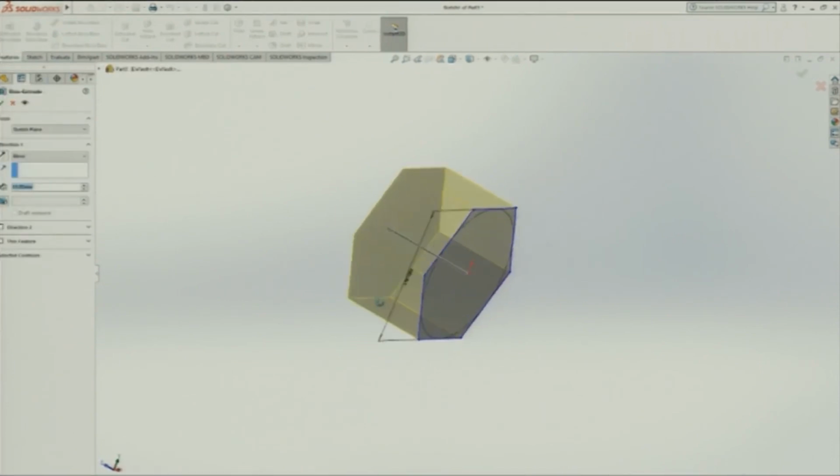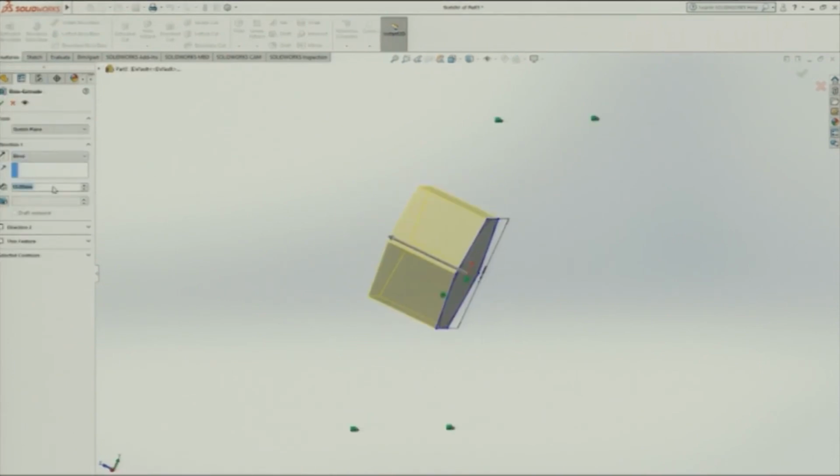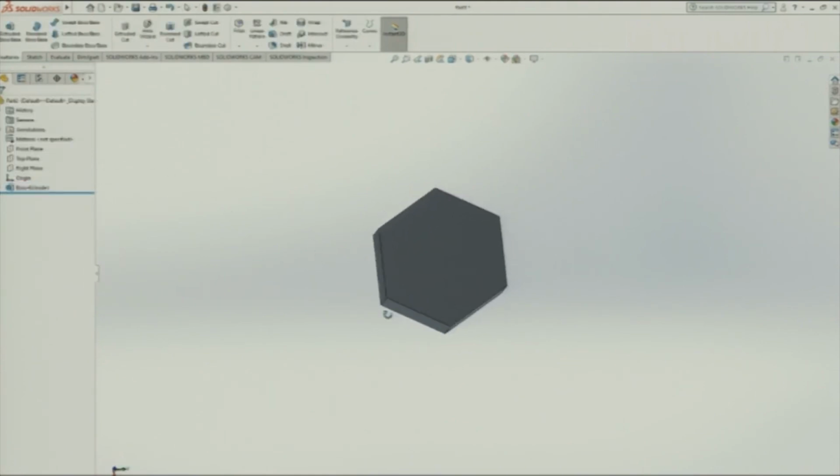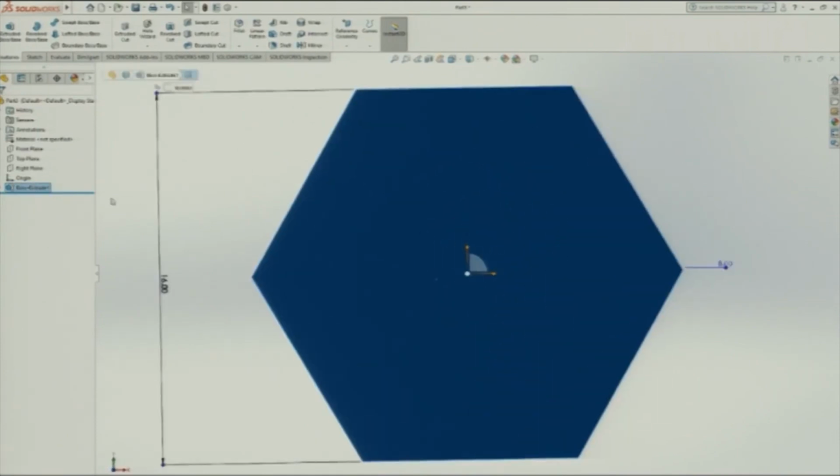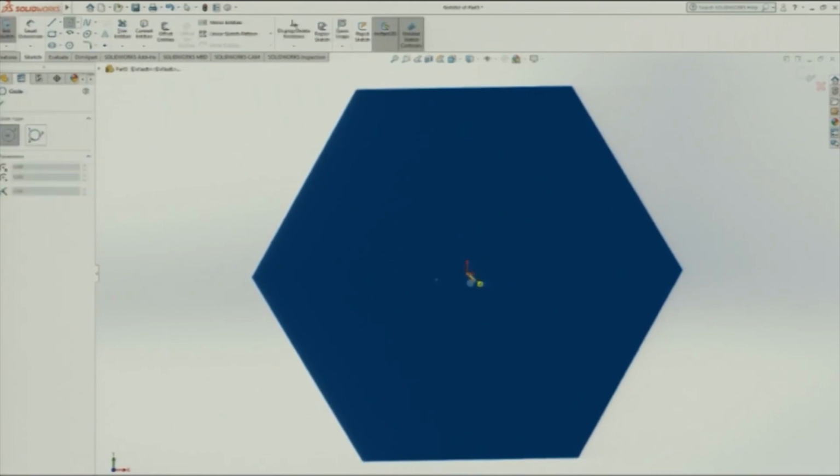So let me extrude it. This is extruded to size 10, which is a little smaller, 5 would be lower. I can put 8 mm, that is okay. So this is, I would say, the base for my nut. I need to now put again the similar operations.